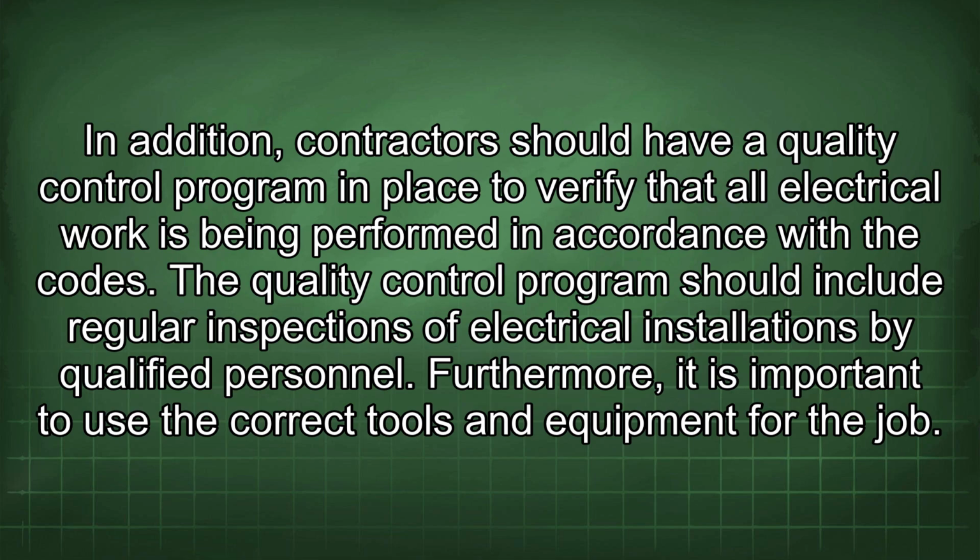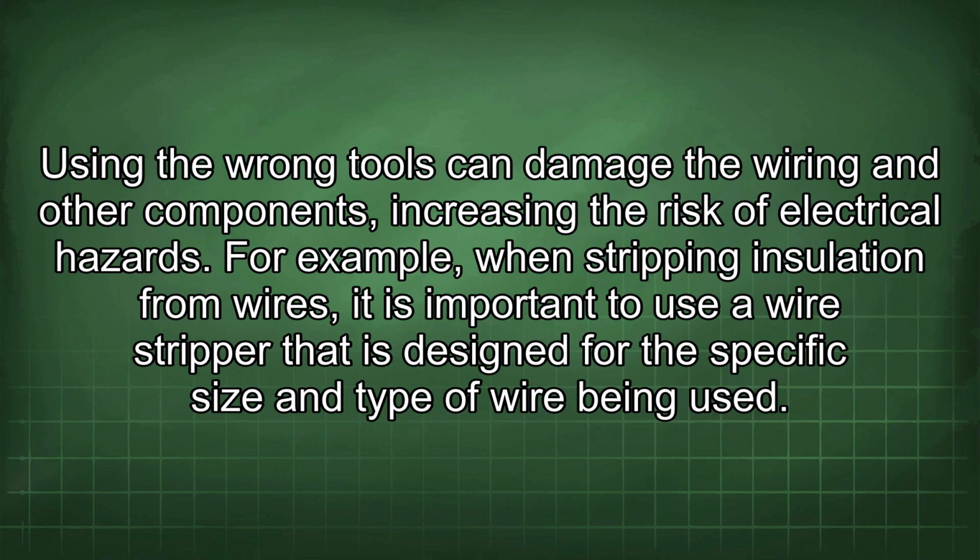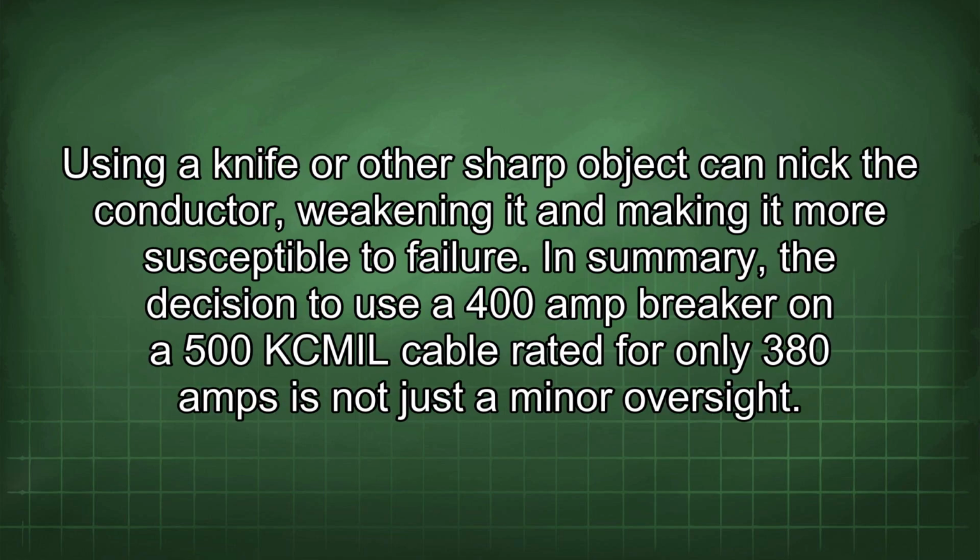Furthermore, it is important to use the correct tools and equipment for the job. Using the wrong tools can damage the wiring and other components, increasing the risk of electrical hazards. For example, when stripping insulation from wires, it is important to use a wire stripper that is designed for the specific size and type of wire being used. Using a knife or other sharp object can nick the conductor, weakening it and making it more susceptible to failure.